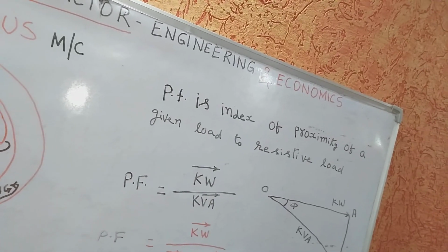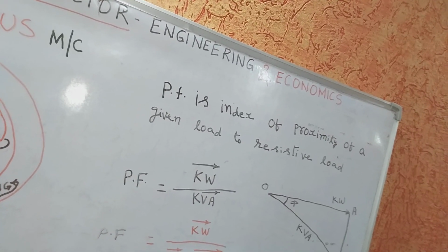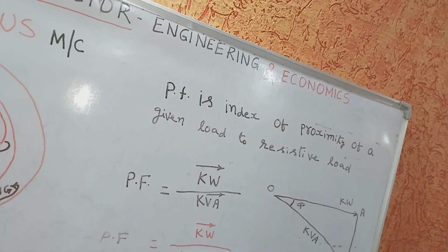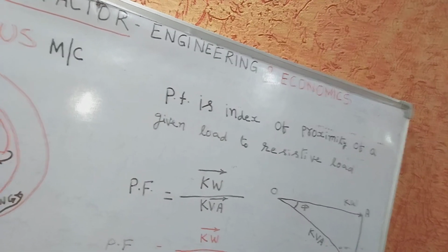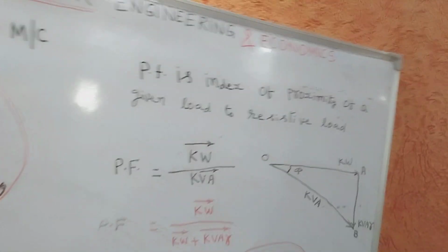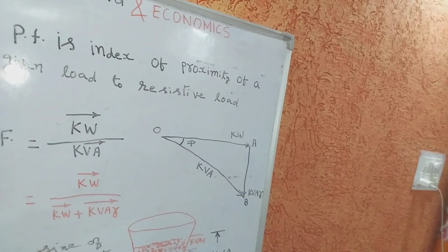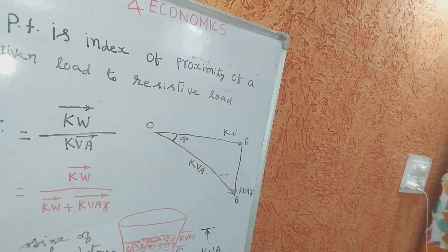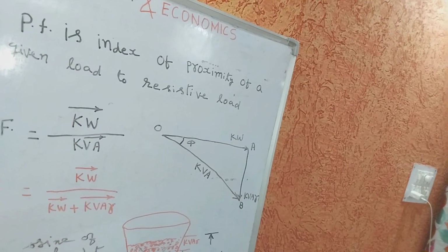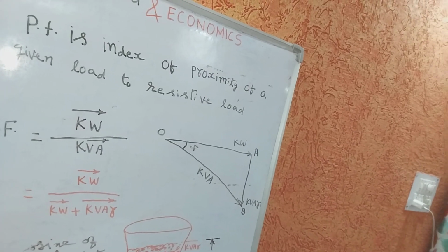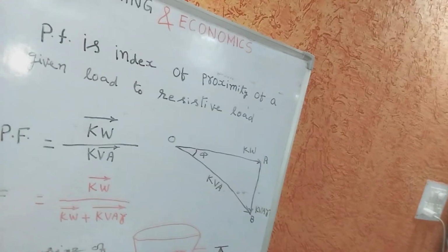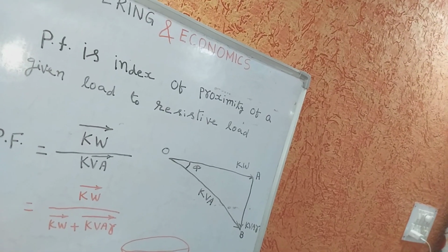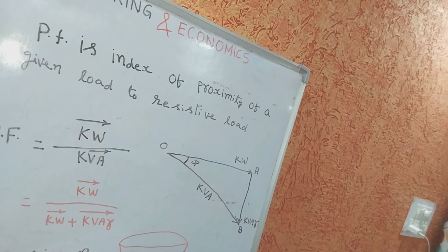The use of shunt reactors at the sending end of the line to compensate the capacitive current is sometimes necessary. For induction motors, it is normal practice to avoid self-excitation by limiting the size of any parallel capacitor when the motor and capacitors are switched as a unit.